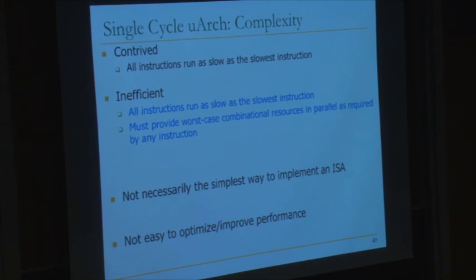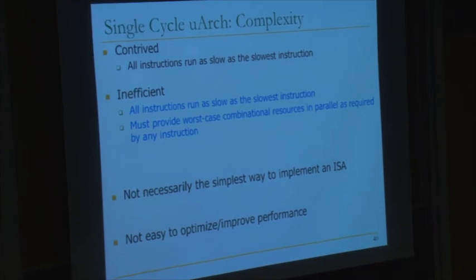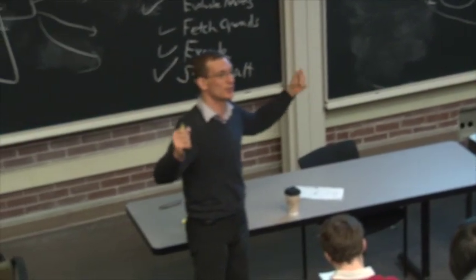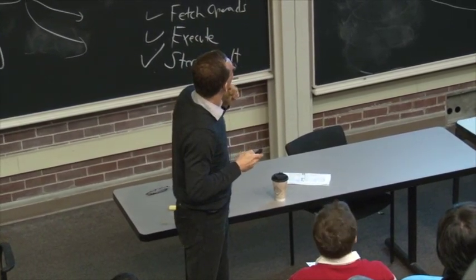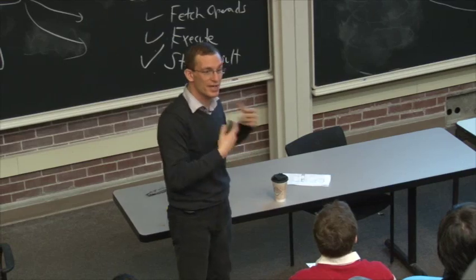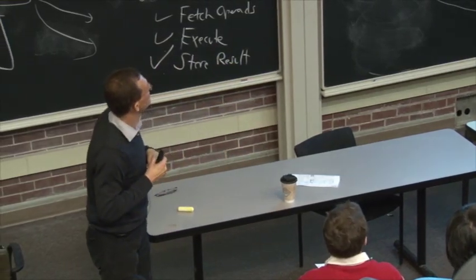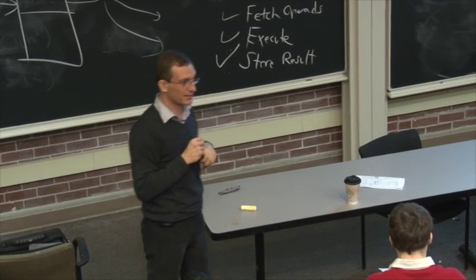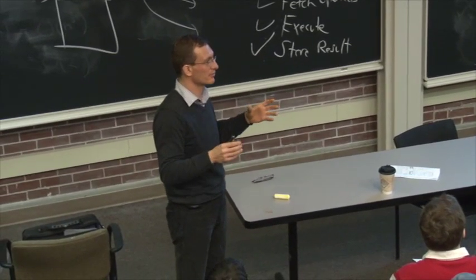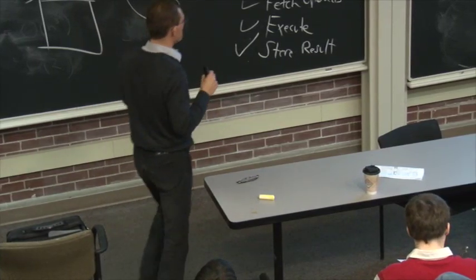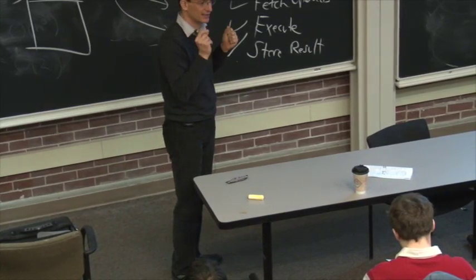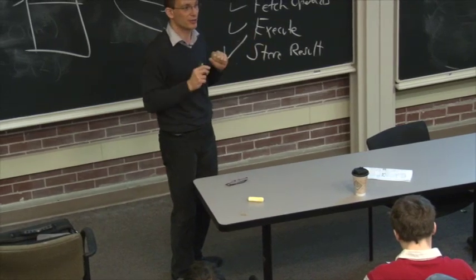Whereas if you took multiple cycles, you could reuse some of those resources. So your hardware cost may be very high with a single cycle microarchitecture because you cannot reuse resources across the execution of the same instruction, right? Yes, so you need to replicate a resource if it's needed more than once by an instruction during different parts of the instruction processing cycle. If you need the adder, for example, multiple times, you cannot just have a single adder because you have to do two adds, for example.